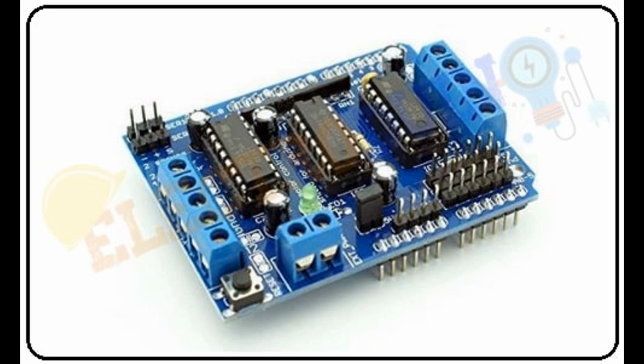2. Basic operation of VFDs. VFDs typically consist of 3 main components. Rectifier converts AC power from the power supply into DC. DC bus smoothens the DC signal to maintain a stable voltage. Inverter converts the DC back to AC with a variable frequency and voltage to drive the motor. The VFD adjusts the frequency of the output AC by controlling the inverter, which determines the motor's speed and torque.